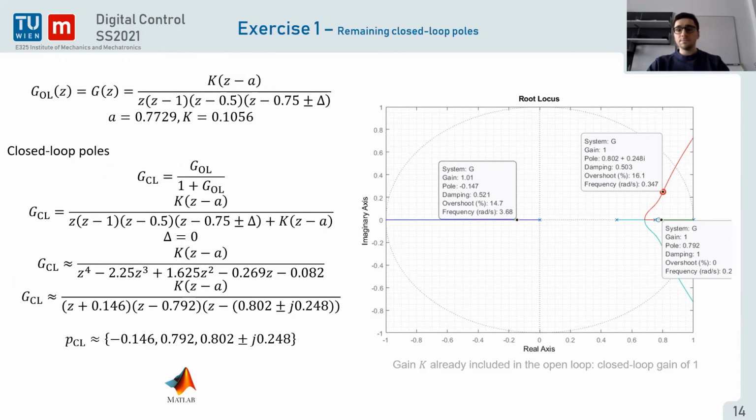It's quite nice that you mentioned it today: when you design a controller with the root locus method, the plant zeros will always stay the same. So if you have a zero of the plant that is quite slow and that completely defines the output of the system, then you cannot change it.